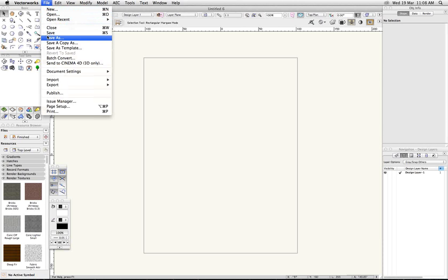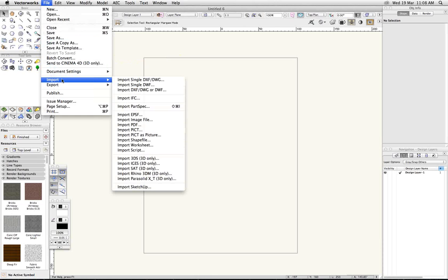So my assumption in this scenario is that we have acquired property lines, existing buildings, and so on from DWG, the surveyor's GPS points as a text file, and that's going to be the basis of our site model, and a geo-referenced air photo, which is again becoming more and more common. Many municipal governments where I am have them available, probably where you are as well.